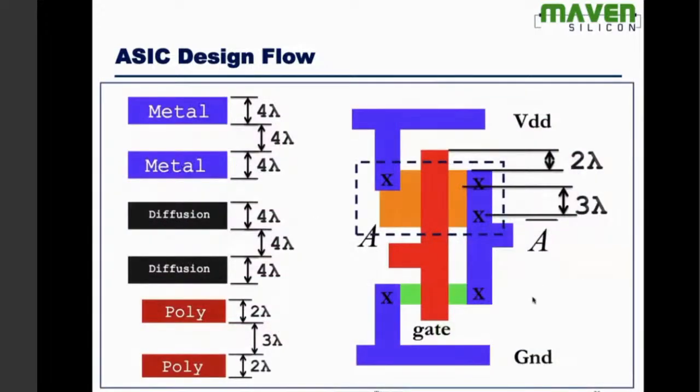For design rule check, we take the stick diagram, and we look at whether we follow the fabrication standard. For example, we want to realize the chip for a particular technology, let's say 12 nanometer. Then the fabrication defines certain standards for 12 nanometer. This is how basically we have to create the layout.